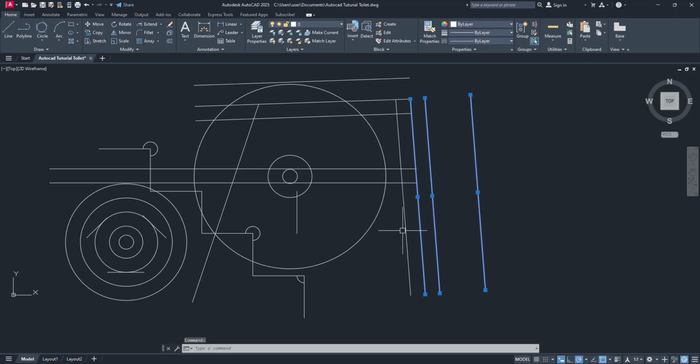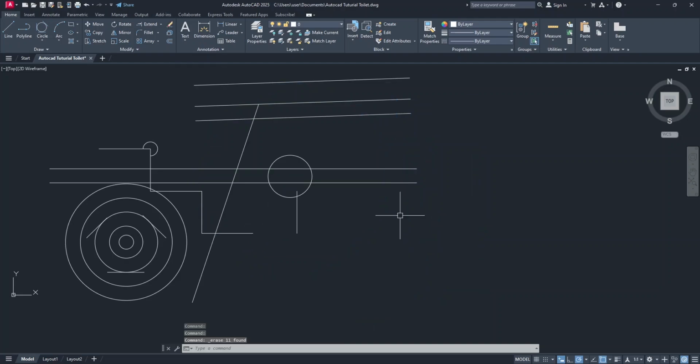You can continue selecting lines individually or use that crossing selection and touch whatever you want to add to the selection, or use a window selection which, unlike the crossing, only selects whatever is fully inside the window, like that small circle. Click here like this one, click here like these two ones, click and touch these two, they got selected. Simply select erase and they are all gone.